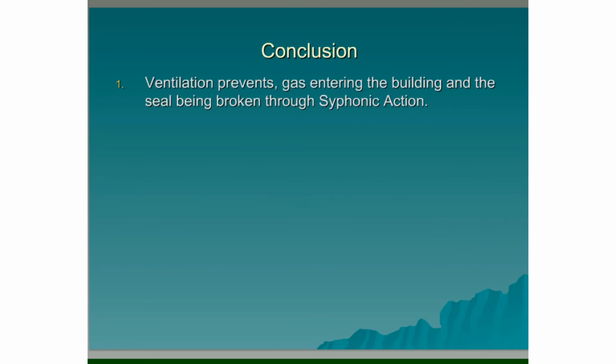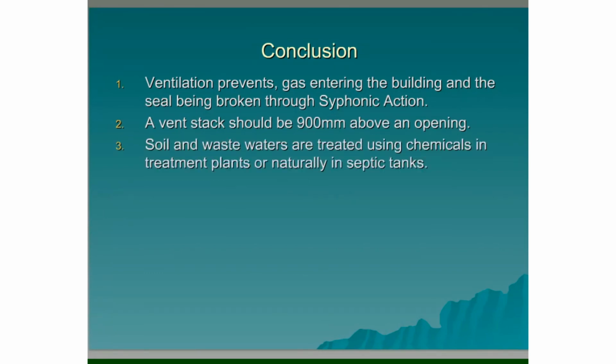Conclusion. Ventilation prevents gas entering the building and the seal being broken through syphonic action. A vent stack should be 900 millimeters above an opening. Soil and wastewaters are treated using chemicals in treatment plants or naturally in septic tanks.